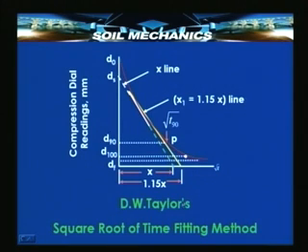All that we now need to do is draw another line, this yellow line, which will have abscissa 1.15 times the abscissa of the tangent starting from ds, and that is precisely what is shown here. If this tangent straight line is denoted as the x line, then this yellow line is nothing but the x1 line, which has abscissa 1.15 times those of the x line.